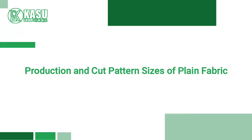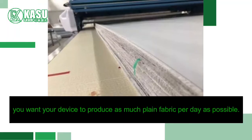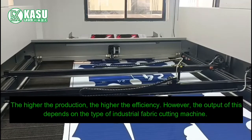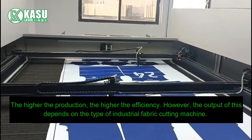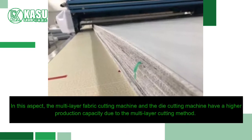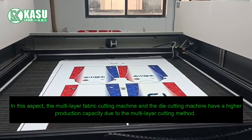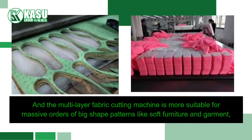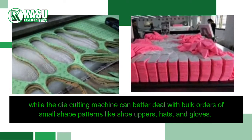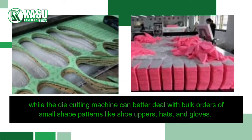Production and cut pattern sizes of plain fabric. When using industrial fabric cutting machines, you want your device to produce as much plain fabric per day as possible. The higher the production, the higher the efficiency. However, the output of this depends on the type of industrial fabric cutting machine. In this aspect, the multi-layer fabric cutting machine and the die cutting machine have a higher production capacity due to the multi-layer cutting method. And the multi-layer fabric cutting machine is more suitable for massive orders of big shape patterns, like soft furniture and garment, while the die cutting machine can better deal with bulk orders of small shape patterns, like shoe uppers, hats, and gloves.